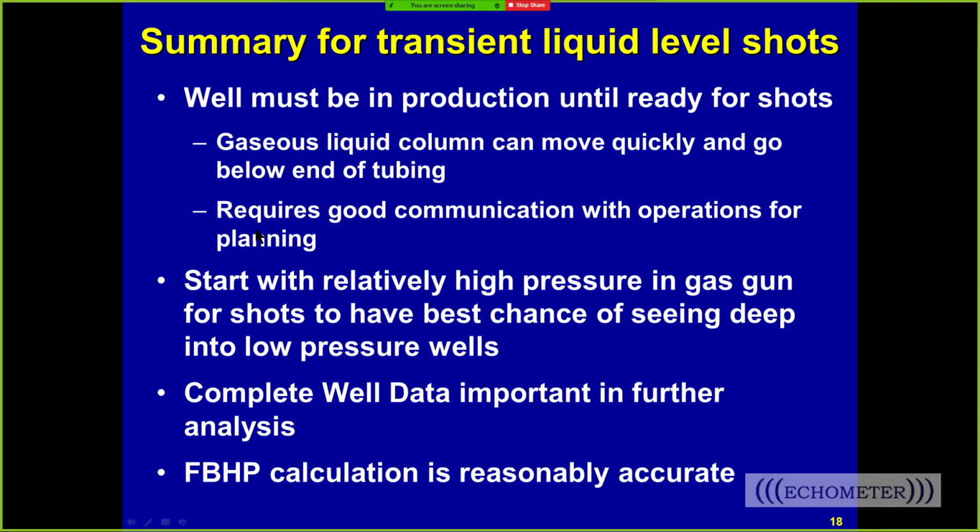Why would it say that? Because if you just go out there and say shoot that fluid on that gas well, and the operator goes out there and shuts the well in, sets the tubing in to get ready to hook his gun up, and he drains some fresh liquid off the valve, and he does some other things, and he hooks his gun up. By that time, the conditions of the well have changed, and it's not going to be representative of the normal conditions of the well.